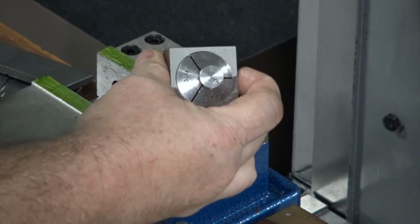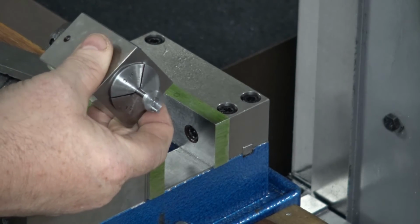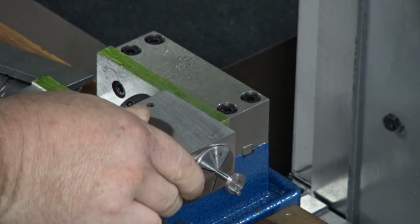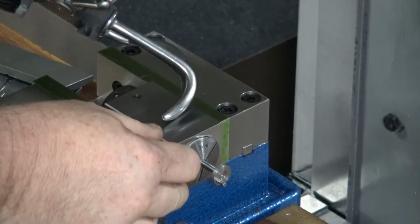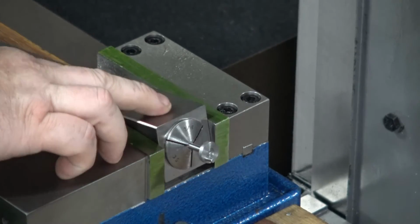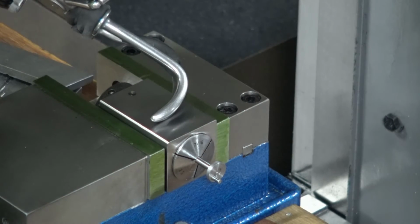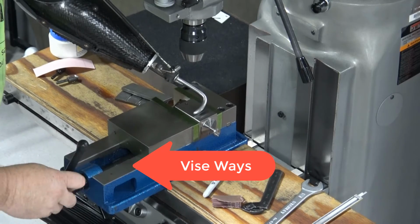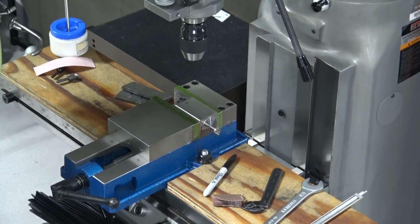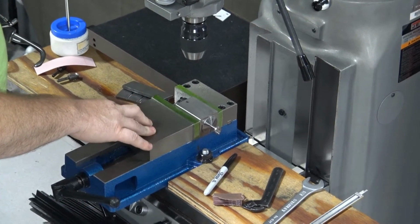So now we're going to spin it back around so that you can see I've got enough sticking out. It's clamped plenty securely, right? I want to make sure that I have pressure applied, because if I leave it in here, it could sit in here and rock, right? I want to make sure that it sits flat down here on the ways of the vise. These are the ways of the vise. So if I put pressure down, and then I lock the vise in, if I really want to get crazy about it, I could run an indicator across the top, but I'm not that terribly worried about it, okay?